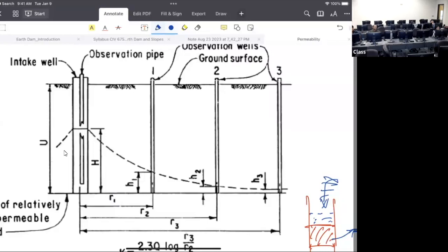This is the reason all our roads are bumpy. The roads are bumpy for a different reason. Roads are bumpy because you have a moisture intrusion, and then some parts get expanded. But what also happens there is, why the wavy pattern? Now the wavy pattern is really distinct on the expansive side.